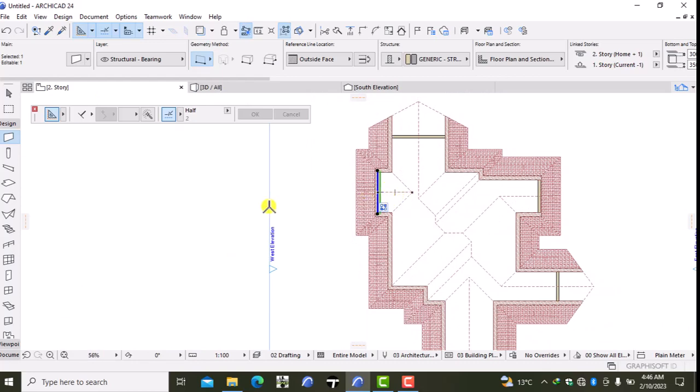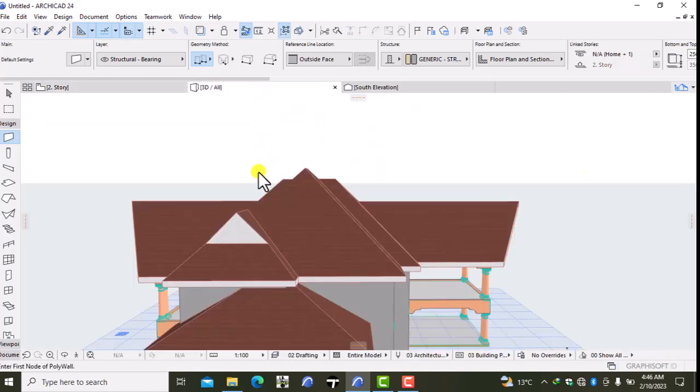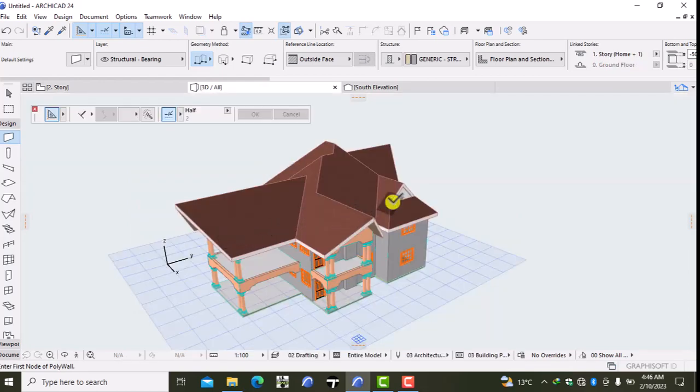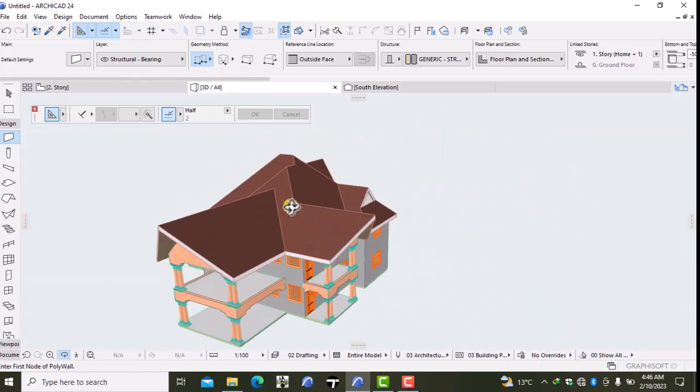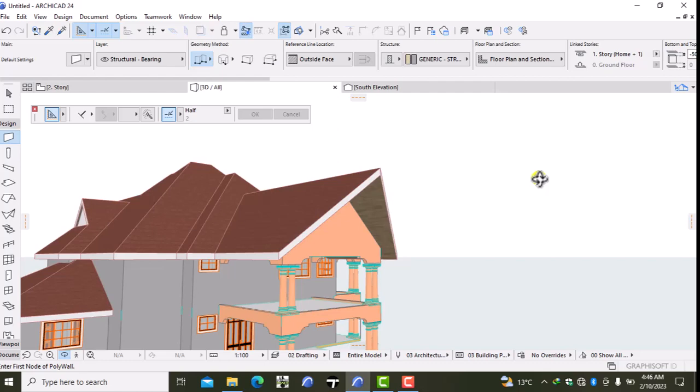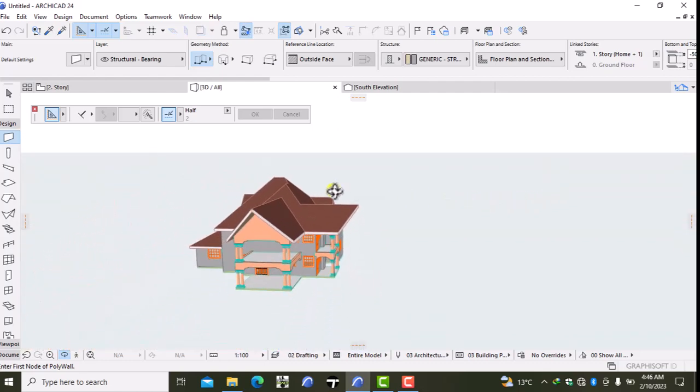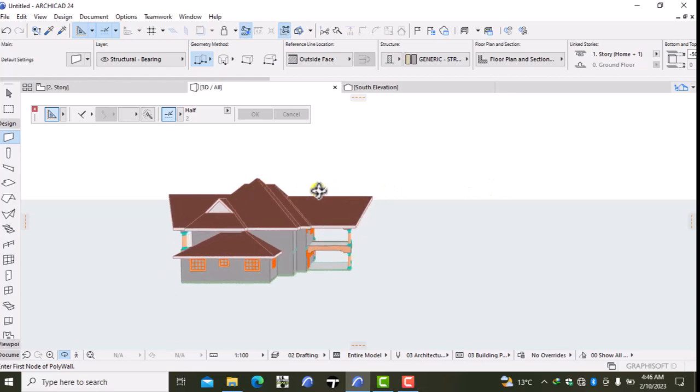and I just need to drag this, Control D, drag it on the inside at a distance of 100. And similarly for this other one over here, Control D, drag it on the inside at a distance of 100. Basically why I'm doing this, I want the fascia board of these other planes to be visible. As you can see now, these fascia boards are now visible. So I have this kind of roofing over them, which I think I can just work with right over there.